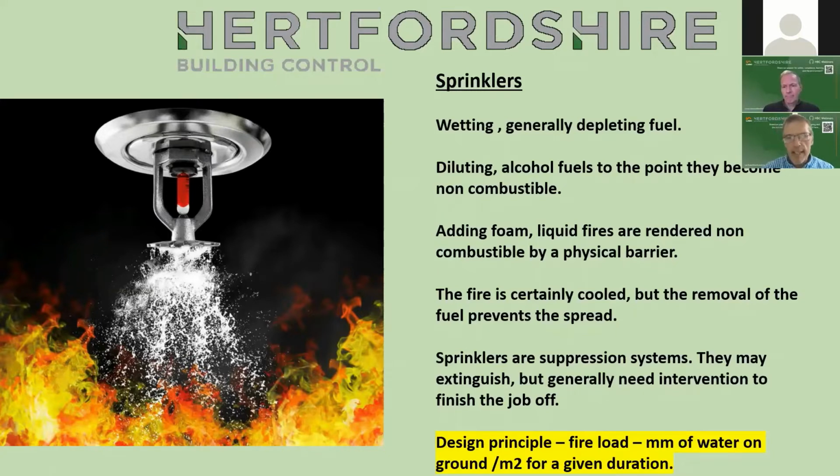If you're going to take anything, sprinklers are a fuel depleting appliance. They deplete the fuel. Yes, they certainly do cool the fire, and so they take an element of heat away from it. There's no doubt about that. But basically what they do, they will wet materials that would combust and turn them into incombustibles. So if it's cardboard or carpet, that carpet and the cardboard will be wetted by the sprinklers, and that will reduce the growth of the fire. And yes, of course, it will